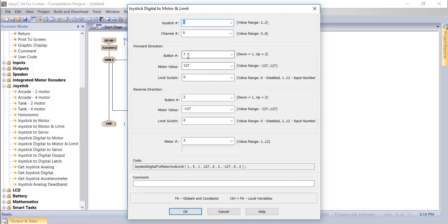So I've plugged in my bumper switch, and so when I bring the lift down, I want it to engage the limit switch. The limit switch is going to be plugged into digital motor port 1. So I put it there, and if I don't have one for the top, I just leave that blank and it'll be fine. But with this code, whenever the lift goes down, I just need to make sure that this part right here, the limit switch, when it's engaged, will stop me from being able to press down any further and possibly damage anything on the robot. So it'll come down, it'll engage, and it'll prevent me from going down, but it will allow me to go up. And that's how we use it here in the drive program.